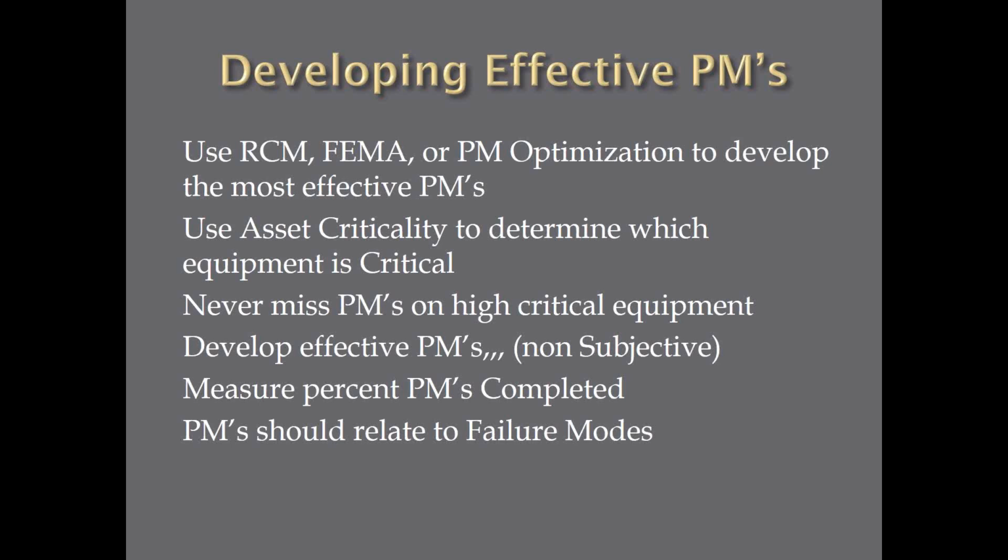Use asset criticality to determine what equipment is critical. And again, we're going to do training on asset criticality in a couple months here. Never miss PMs on high critical equipment. Develop effective PMs that are non-subjective. Remember those subjective PMs. Check the pump.